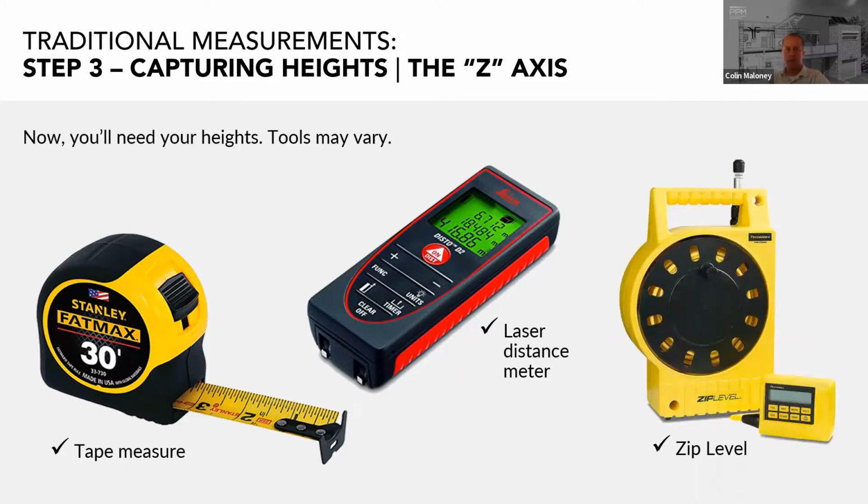The first two tools are ones you've already used probably in other aspects of your plan, but the third is used exclusively to gather height information. It's called a zip level. This is an excellent tool invented, distributed, and repaired if needed by a company out of San Diego. I'm not aware of any other version of this tool. It uses displacement to read heights anywhere within a 50-foot radius. It's got a cable in the middle of it, as you can see. The readout dial is below.